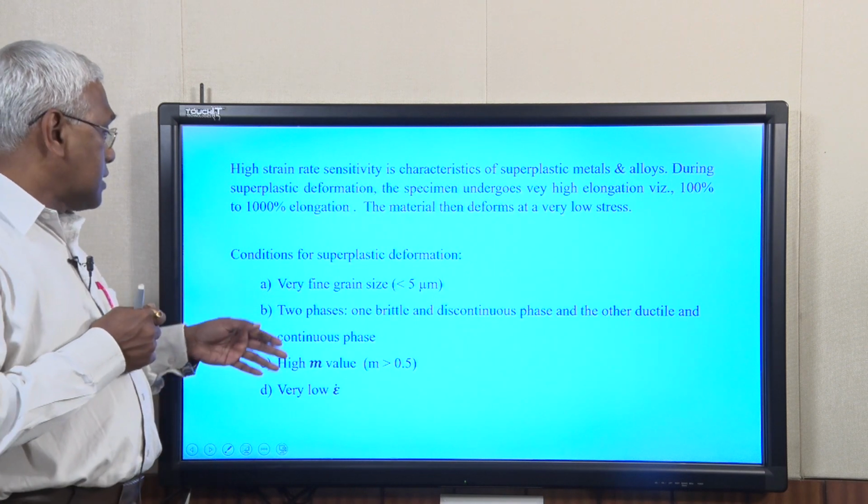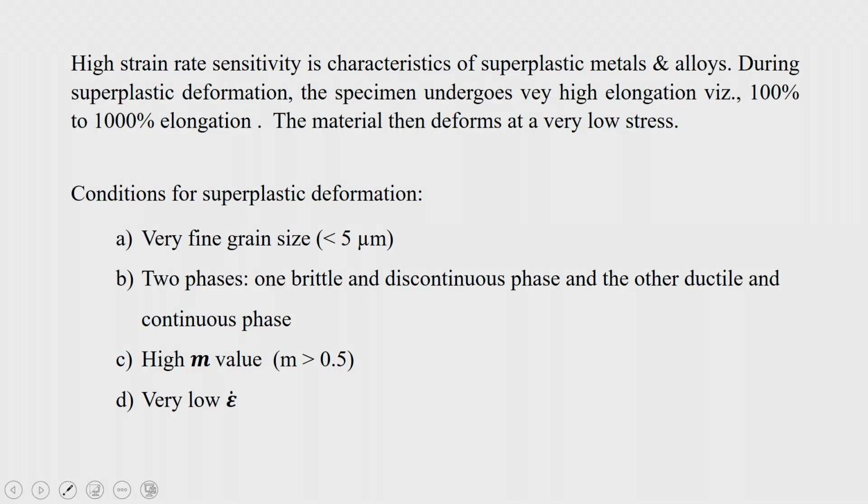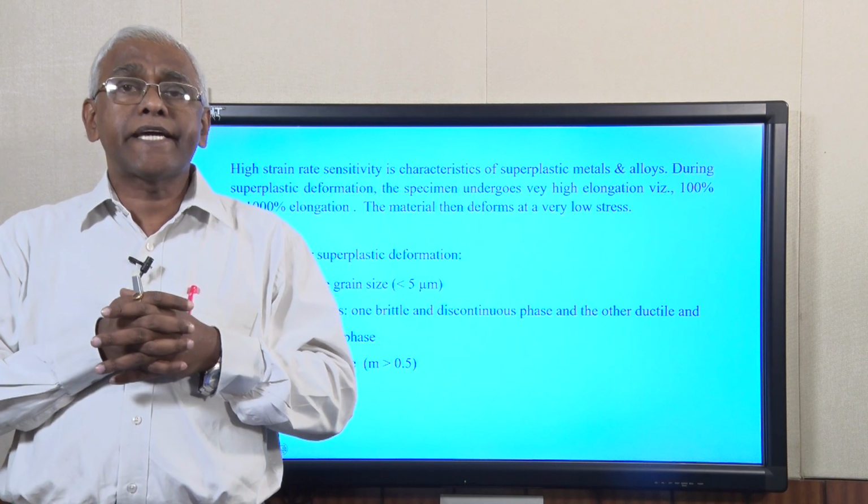And the material should have a very high value of strain rate sensitivity index, that is, the m value should be more than 0.5, and the strain rate should be very, very small. At a very high strain rate it may not work out. So strain rate has to be very small. In that case you can deform the material without any necking.